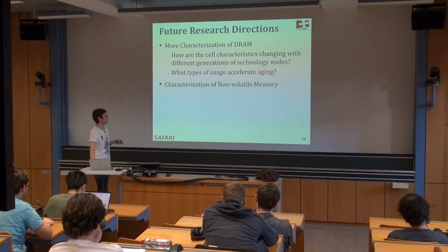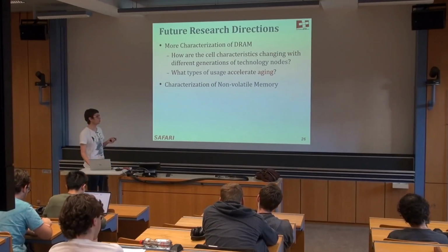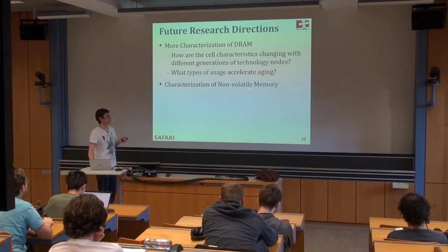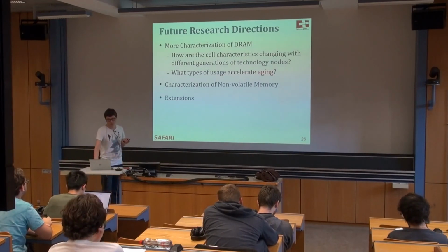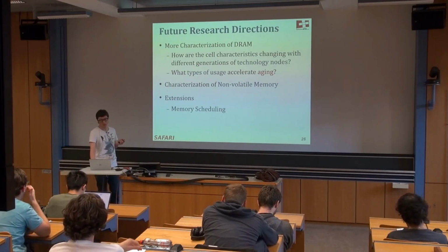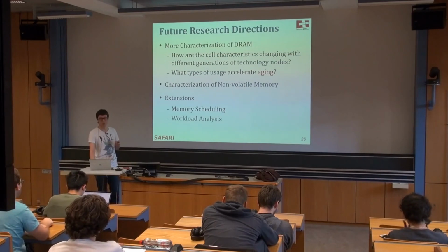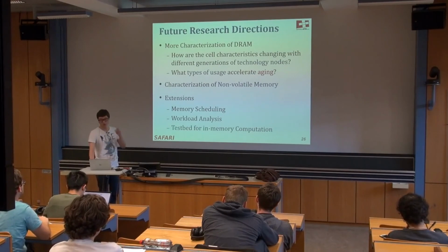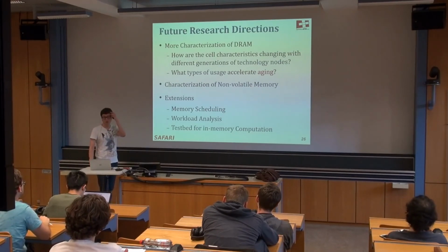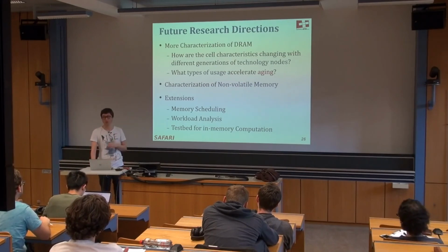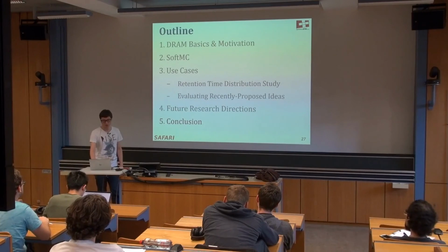By extending SoftMC, it should also be possible to experiment with non-volatile memories. Some other extensions could be implementing some logic to support different memory scheduling algorithms, and developing a test bed for workload analysis and in-memory computation. Again, those require extensions to SoftMC. You cannot just do it by writing some code in software. You need to modify the Verilog code on the FPGA.